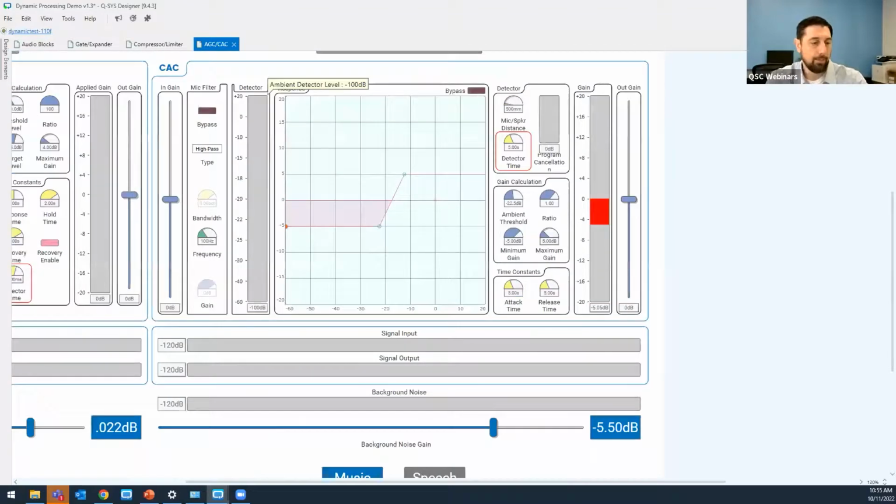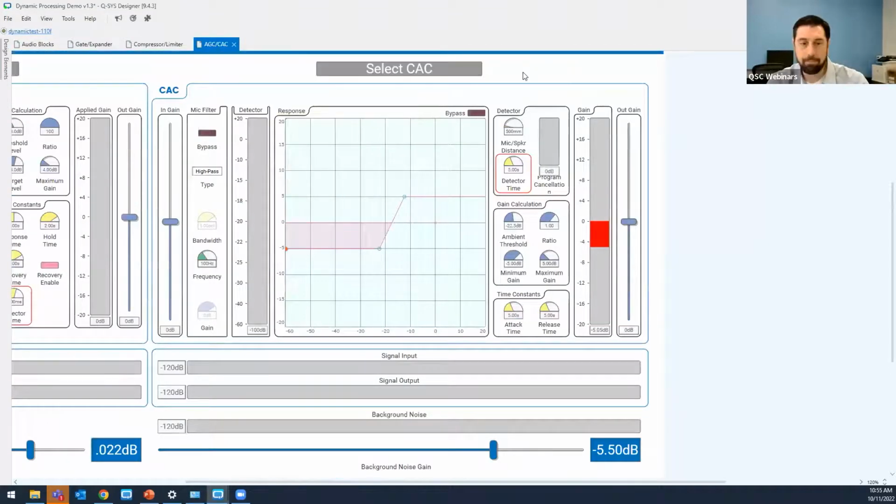All right, so we've got a couple of settings here, some basic settings that we need to set. Distance that the microphone is to the nearest speaker. This is critical because this has to do with setting sensitivity and how it listens for the signal that it's going to cancel out.